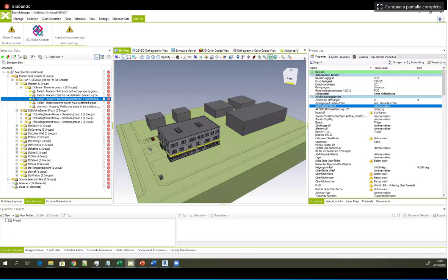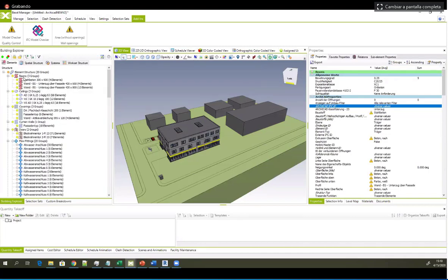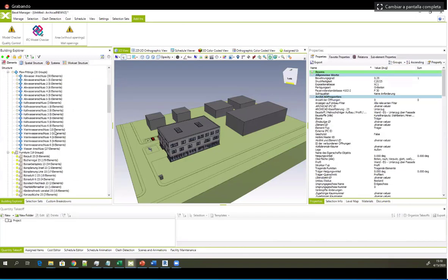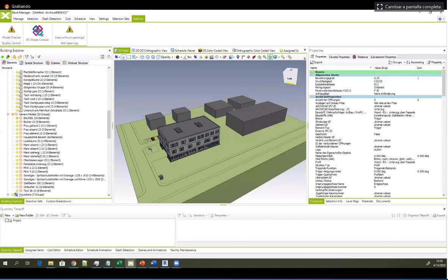What are the differences between categories and the families? Okay. So this is another question. Categories are the higher level of hierarchy. So these are the different IFC types and, let's say, subtypes or specific entities of IFC elements. So always you see the beams, and these are all beams in your project, but of course you have different types of the beams, and each beam has specific, let's say, height and width or dimensions. Or your walls have specific types. The walls is a category, and each wall has a specific, let's say, subtype. So you have concrete walls, partition walls, masonry walls, and so on. So these are different levels of hierarchy.